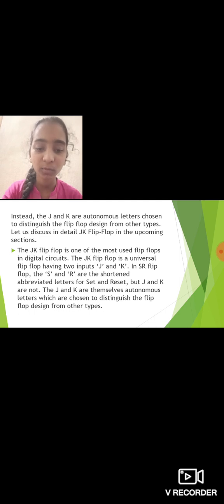Unlike the JK flip flop, the basic SR NAND flip flop circuit has many advantages and uses in sequential logic circuits, but it suffers from two basic switching problems. First one is when set is equal to 0 and reset is equal to 0. Second one is when the set or reset changes states. Then to overcome these two fundamental design problems with the SR flip flop design, the JK flip flop was developed.